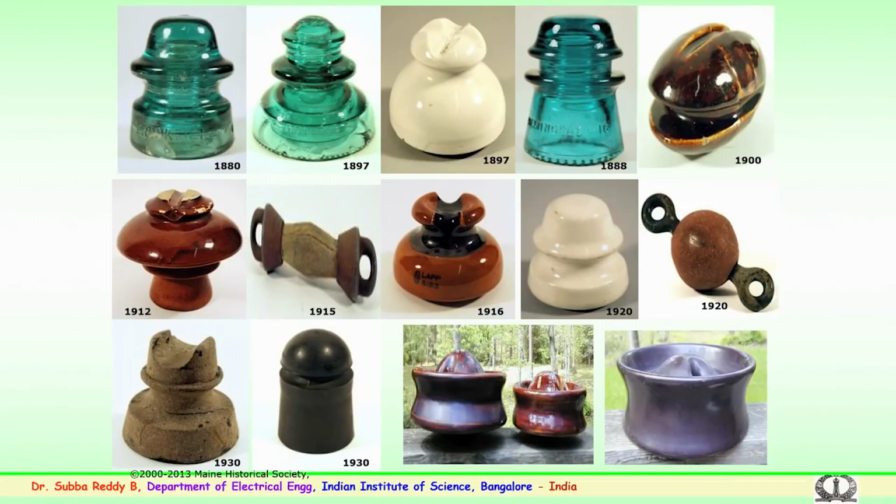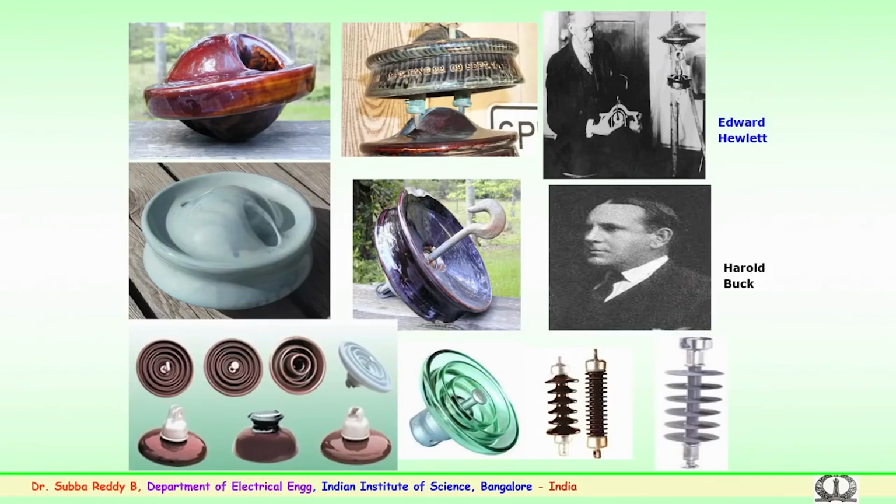It so happened that up to a certain voltage the problems did not exist. Later on, when the voltage levels increased, there used to be a flashover on the surface, and this is how the insulator technology has come. You can see several pin type insulators since inception. Various models, various creepage lengths and various types were developed by various manufacturers and were used for several decades. These are again an improvement aspect for the porcelain or ceramic insulator.